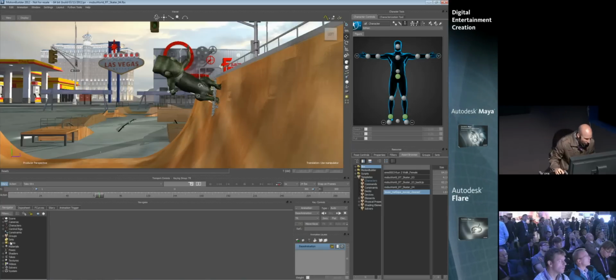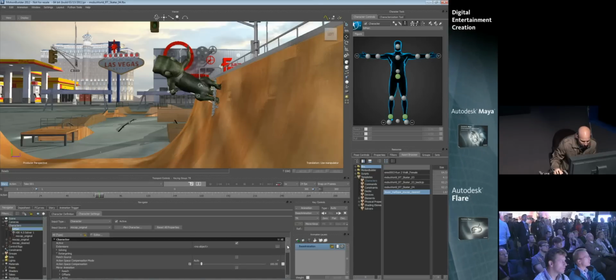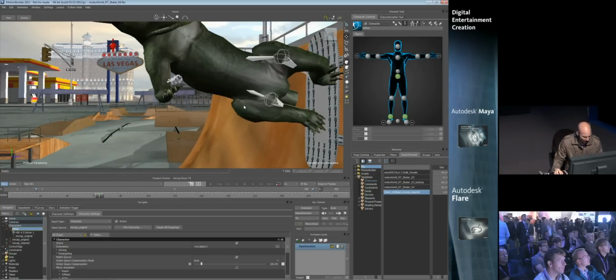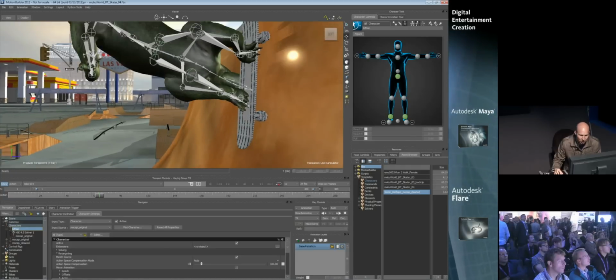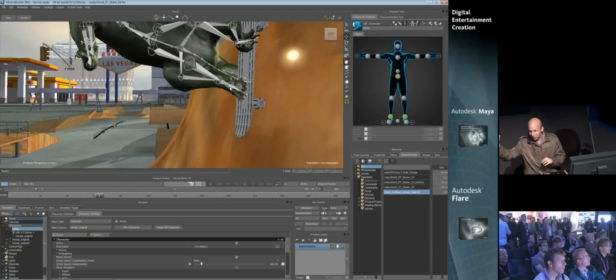We're going to jump into the character node for this lizard, and we're going to change it to match world position. As soon as I do that, you can see that it's now matching world position. And look at the legs here. Notice that this lizard's leg is no longer matching joint angle. It's actually coming down and touching the same position as where the original motion capture's foot is.